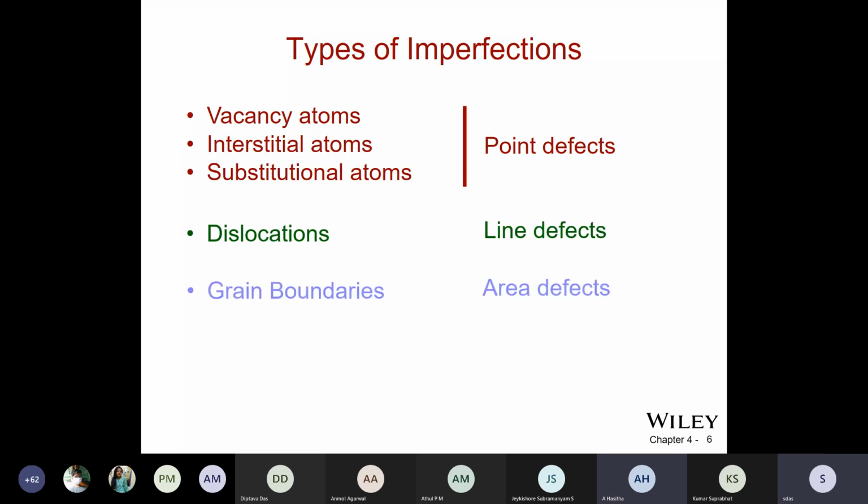Sir, how are the nuclei growing to form a big grain? That will be taught in detail in the next chapter. For the time being, in a liquid, by statistical fluctuation, suddenly a few atoms of the liquid momentarily take the orientation of the corresponding solid. Momentarily means for a fraction of a second. And then they move away.